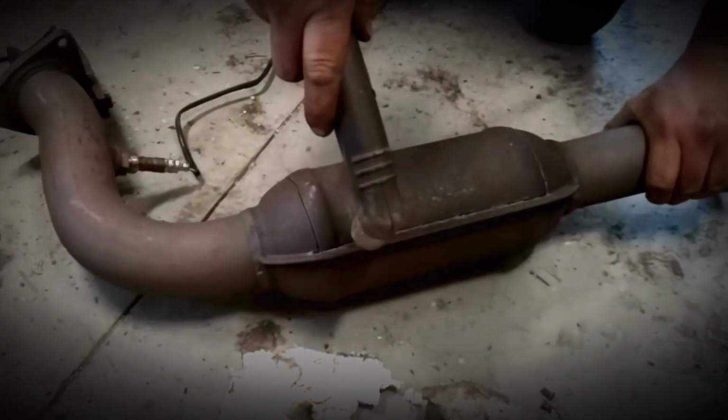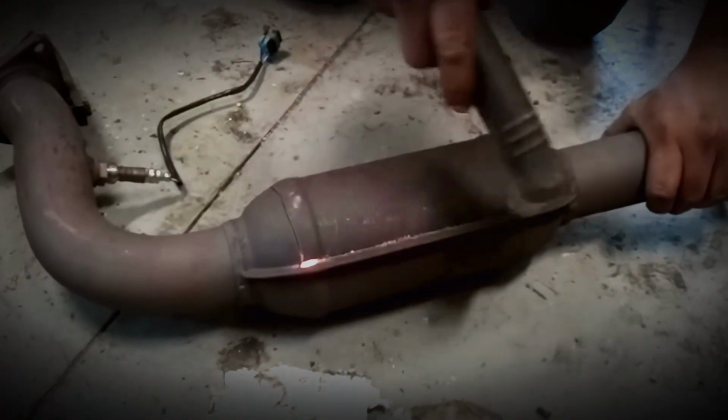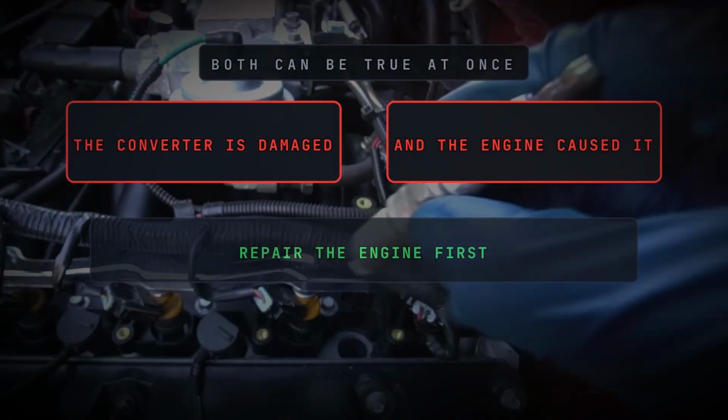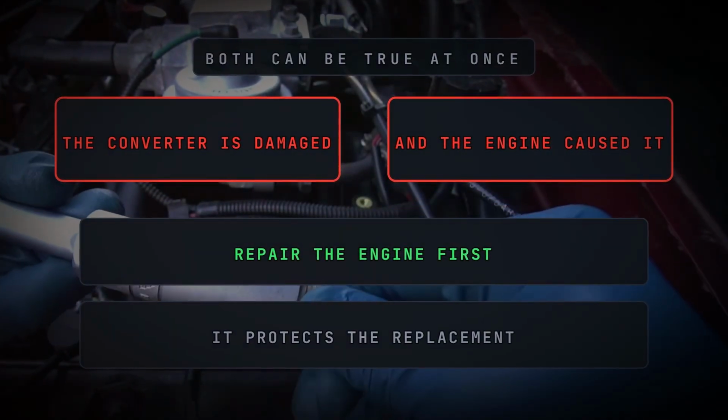Do not assume the converter is healthy simply because you found a misfire, rich condition, or oil problem. Both faults may exist at the same time. The converter may already be damaged. Repairing the engine protects the replacement and allows the catalyst monitor to be evaluated under valid conditions.